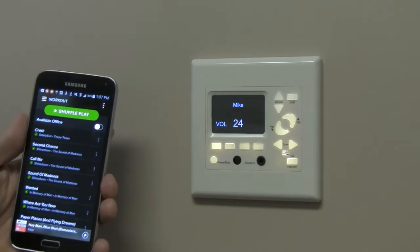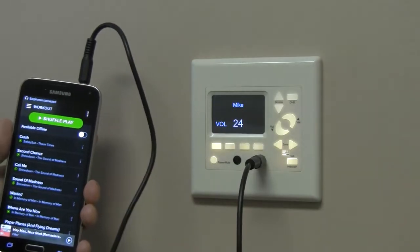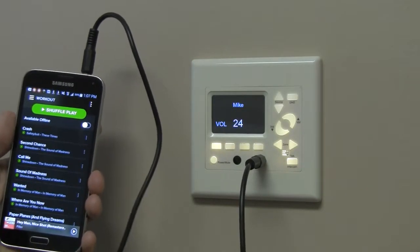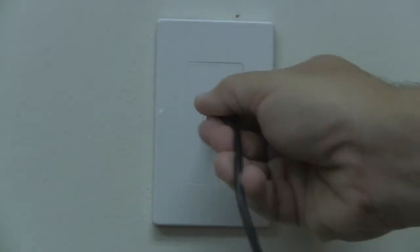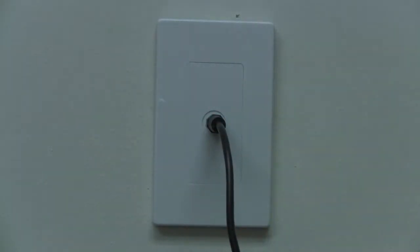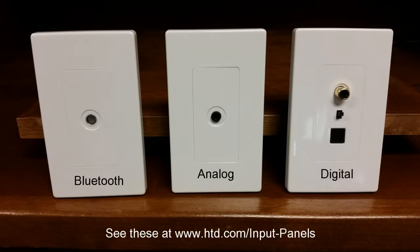To connect a source within a zone, with Lync you have several options. You can connect directly to the 3.5mm input on the Lync pad, or you can add a source input panel in a more convenient location somewhere in that zone, typically behind a TV or a nightstand. We offer several models of input panels that provide connections for analog, digital, or even Bluetooth. They connect via Cat5 cable either to the back of the Lync pad in that zone or to the Lync controller if you happen to have run your Cat5 cable all the way back to the central location.